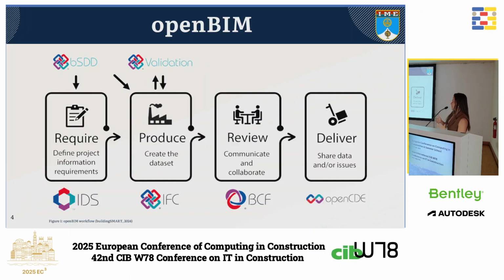But what's openBIM? According to buildingSMART International, an openBIM workflow is any process that incorporates buildingSMART solutions and standards such as IFC or IDS. And we know that each project can define a specific openBIM workflow depending on its goals, but in general, it starts with a definition of information requirements, and they can be defined through an Information Delivery Specification, an IDS.